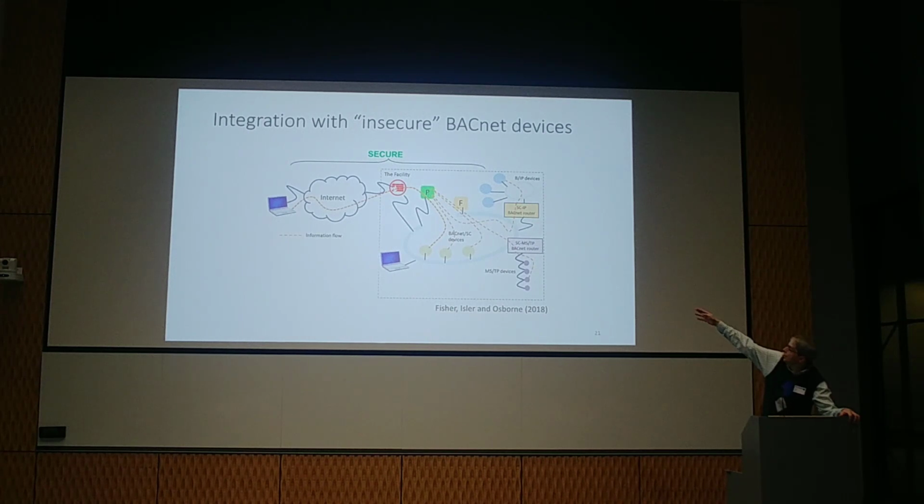Okay. But there are routers in the system. So if you're a BACnet IP device, let's say, those routers are going to route everything. They're not selective. Absolutely. Gotcha. If it's a standard BACnet router, it will allow the BACnet IP devices free access to BACnet SC devices. This is one of the motivations for using authorization in your system. You might decide as a policy that none of the BACnet IP devices are allowed to change any parameter in any BACnet SC device. And you could enforce that using a combination of BACnet SC and OAuth 2, for example.